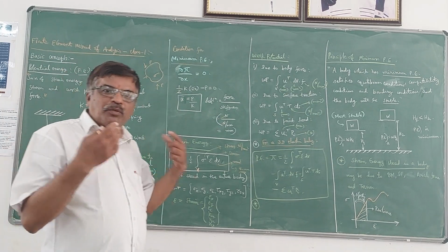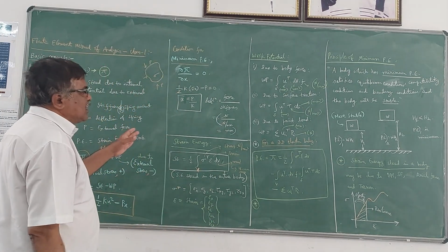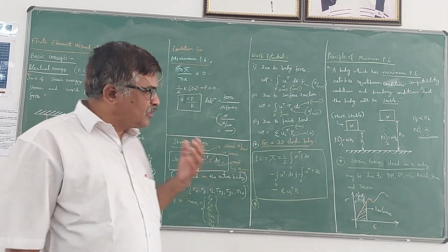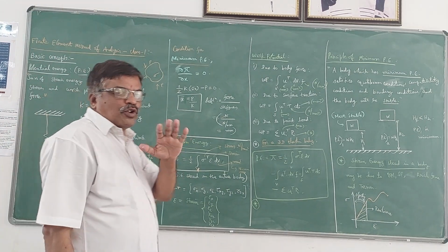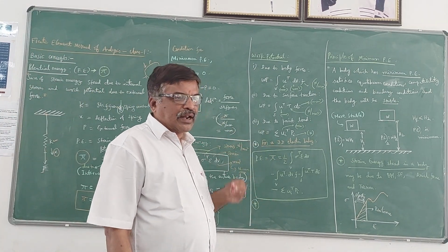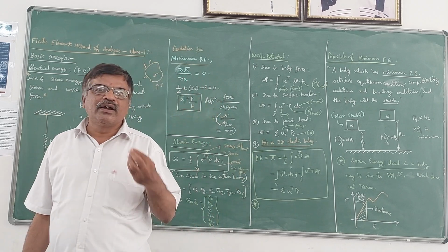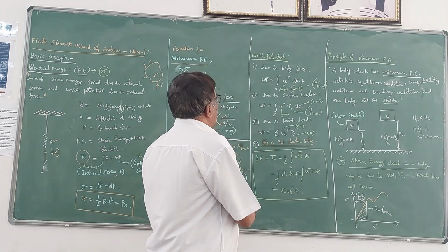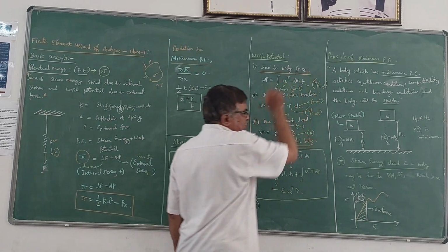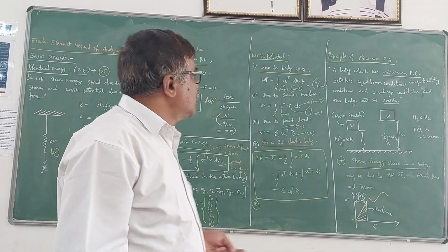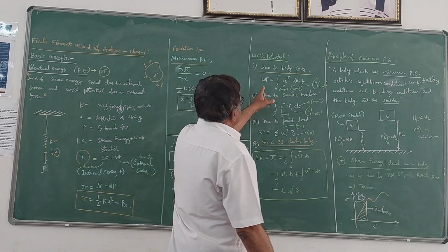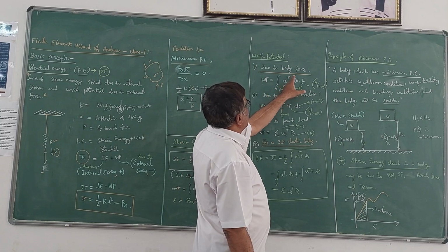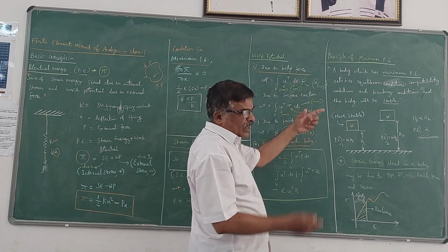Now coming to the work potential, the second part. Work potential can exist in 3 forms. It is always due to the external force. The external force may be a linear force, an area force or a volume force. Like that, 3 ways we can classify. Body force means it acts over the entire volume of the body, so it is three-dimensional. In that case, work potential is expressed as integral over V of U transpose into F into dV.